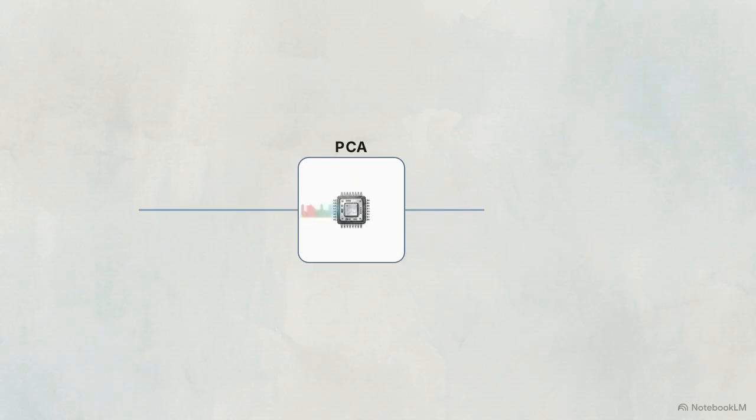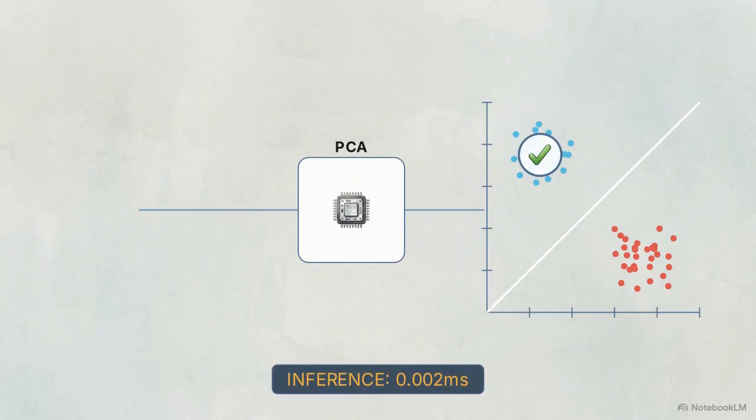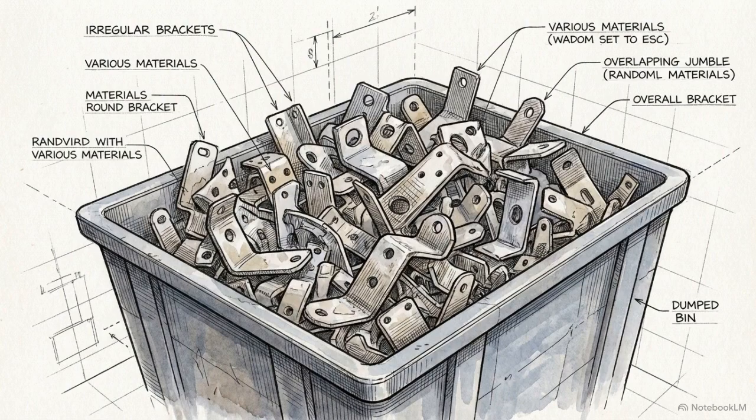This flow diagram tracks visual data concatenated into color channel histograms, compressed through a principal component analysis node, and plotted as distinct clusters in a support vector machine chart. This handcrafted pathway reduces training data demands and executes at ultra-fast inference speeds. Conversely, dynamic inspection tasks, like robotic pick-and-place, present a much higher morphological complexity, requiring a deep learning approach to handle variables in shape and orientation. As shown here, a convolutional neural network restricts the processing load, making deep inference feasible in real time.